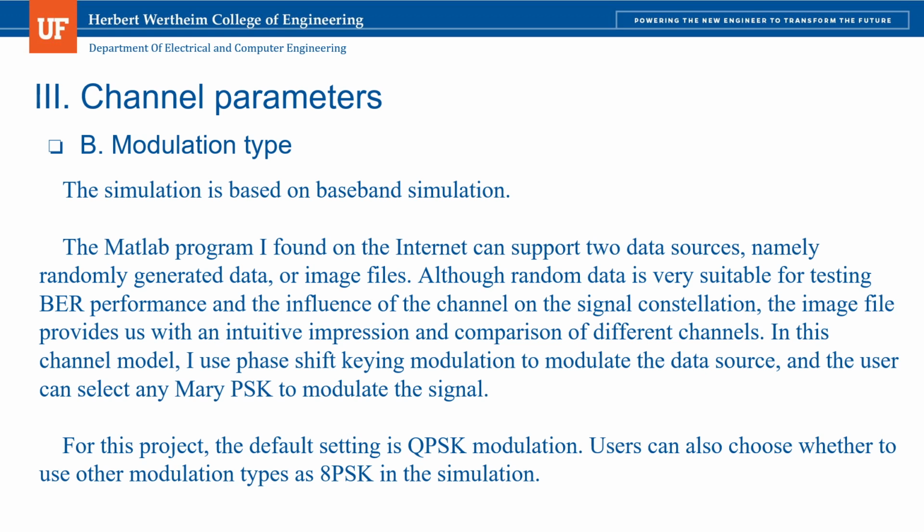In this channel model, I use phase shift keying modulation to modulate the data source, and the user can select any M-ary PSK to modulate the signal. For this project, the default setting is QPSK modulation. Users can also choose to use other modulation types such as 8PSK in the simulation.